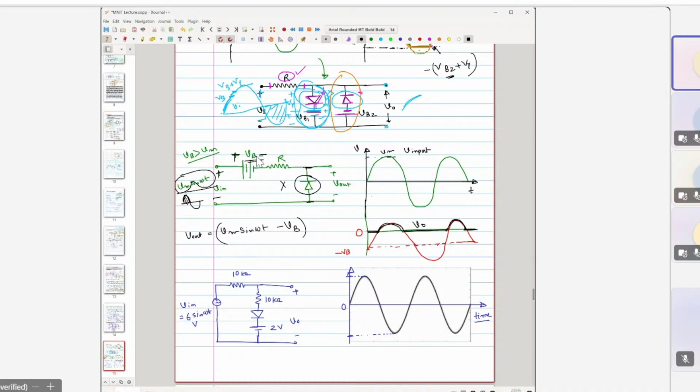And actually what this circuit does is that you can see this is Vm sine of omega t minus Vb, right? So this is Vm, right? So this is 0, right? And this is minus Vb. So from 0, you have to shift that waveform down by Vb, right? So basically then you can shift, and you know this diode only conducts, right?